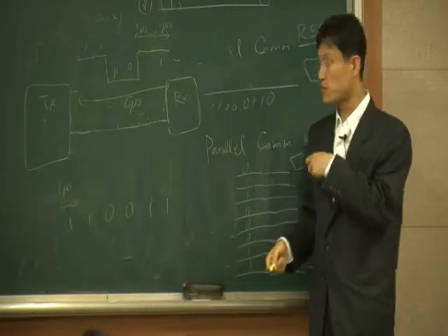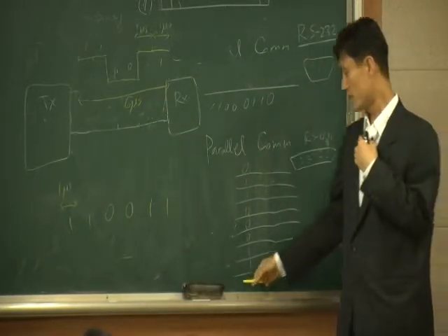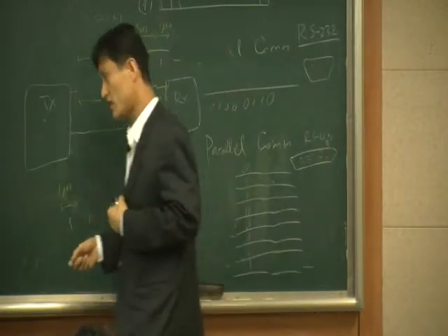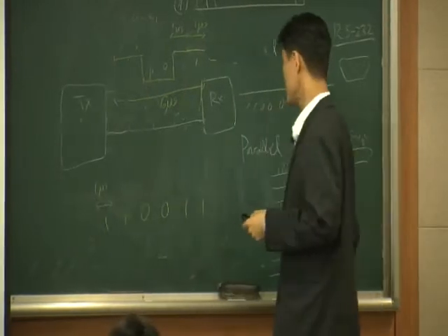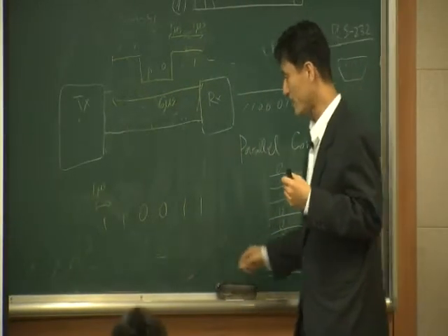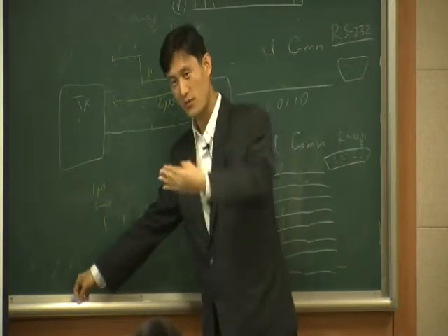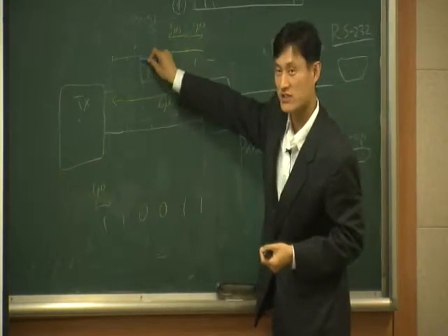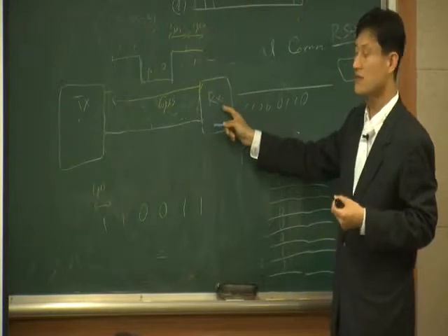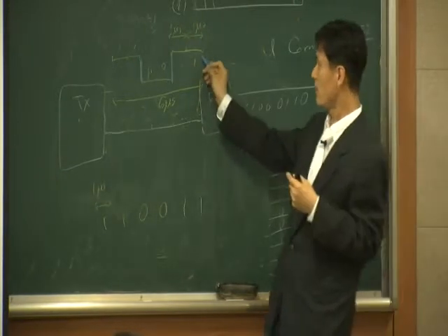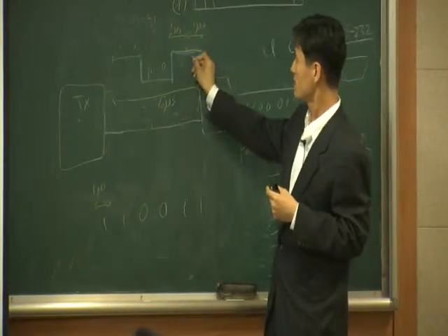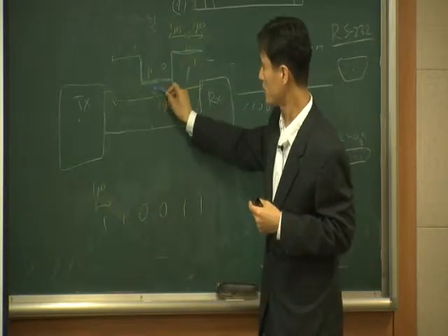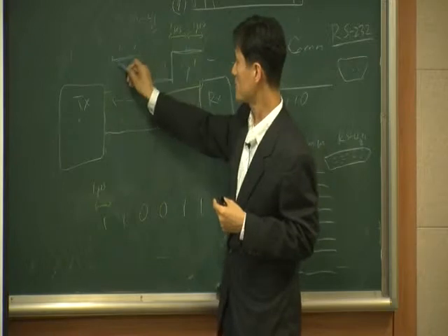That's what we transmit. However, from the receiver perspective, the receiver doesn't know anything about this. So the receiver only detects the edge, drop or up. So this is one edge. There's another edge. In this case, the receiver may be thinking that this is just symbol 1, this whole thing is symbol 0, and this whole thing is maybe symbol 1.